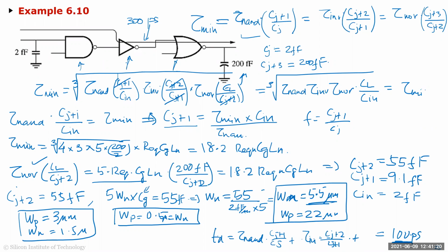Now, in a typical automated process, you don't have access to it. You do what's called ECOs, but at least if you're doing it by hand, or if you're doing ECOs, you can tell if there is a way to optimize it or not. Like for example, if the timing report comes back and says it's 100 picosecond, and you do the critical path analysis and you find out that yes, it is 100 picosecond, I can't do better than that, then you basically are stuck with the technology or the architecture. You have to change either one of them. Otherwise, you're not going to meet the timing, or relax the clock.